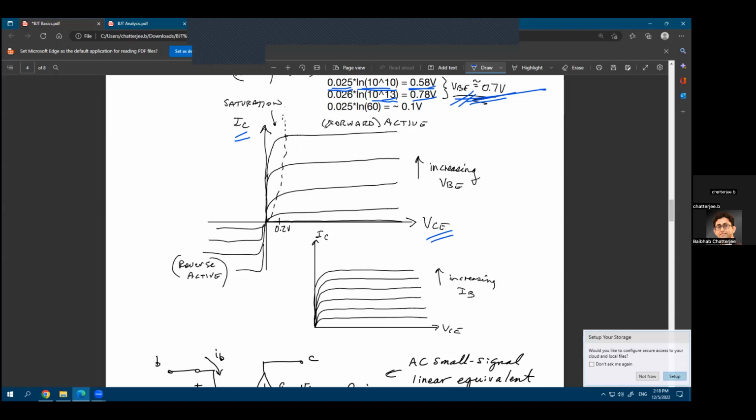And one important aspect here is that usually if you look into books, this region we call the saturation region for MOSFETs. And there is a very good reason to call it the saturation region, right? Why? Because your current was saturated. You see that the current is a constant quantity as you are changing the x-axis. So in case of MOSFETs, we call this the saturation region. Sometimes in the notes you saw that it was also termed the active region. So saturation or active meant the same thing.